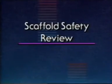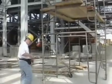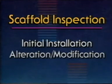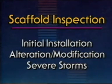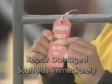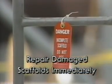Now let's briefly review some of the important points of safe scaffold use. Regular inspection and maintenance is a key element of safe scaffold use. Scaffolds of every type should be inspected by a competent person after any one of the following events: initial installation, any alteration or modification, a severe wind, rain, ice, or snowstorm. If a scaffold is identified as damaged or flawed in any way, it should be taken out of service until all necessary repairs can be made.